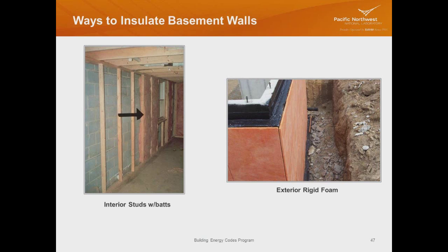I can fur out on the interior and have insulation between those furring members, and that would be considered cavity insulation in my basement wall. Or I might have a foam board on the exterior, and I'd enter it as continuous insulation in REScheck.